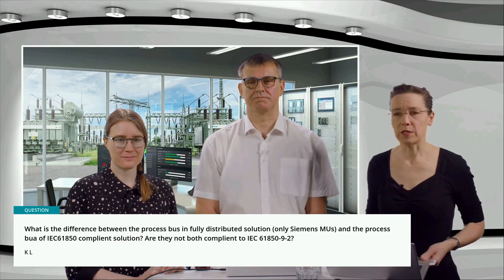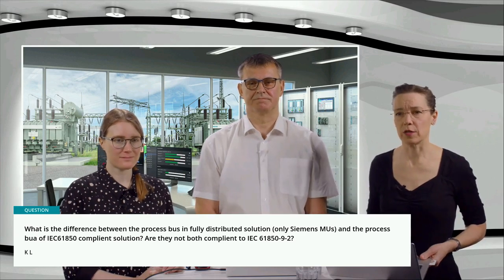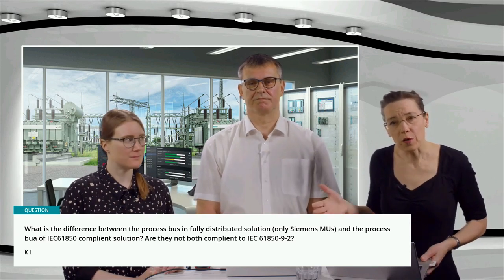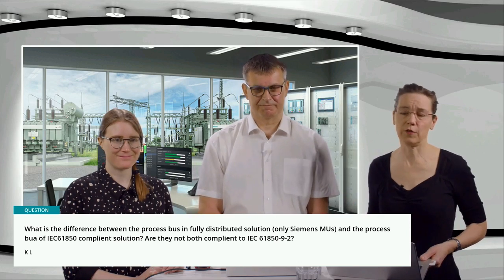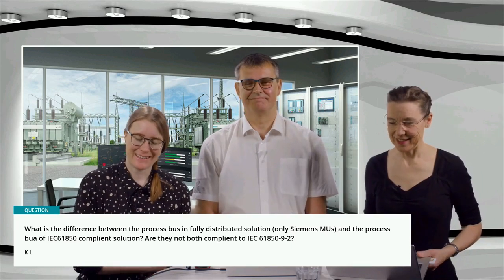Kale wants to know, what is the difference between the process bus in a fully distributed solution, so with only Siemens MUs, and the process bus of an IEC 61850 compliant solution? Are they not both compliant to IEC 61850-9-2? Yes, both are compliant to the IEC 61850 standard.